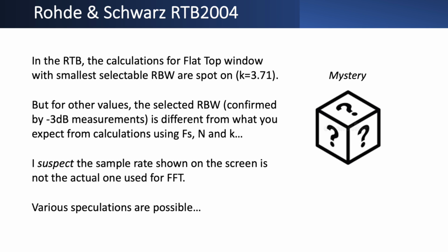Could Rohde Schwarz be using oversampling here, and if so, why would they do so? Normally, for a higher resolution bandwidth, you would simply increase the sampling frequency. But by doing so, you can possibly generate different spurs that come from aliasing, and maybe Rohde Schwarz didn't want the look of the spectrum to change when you alter the resolution bandwidth, and decided to oversample and kind of emulate the resolution bandwidth after that. And if this is true, then it's something like a second step, and that may remind some of us of the so-called video bandwidth settings that we know from the classic spectrum analyzer, which is also a second step carried out after the regular analysis.